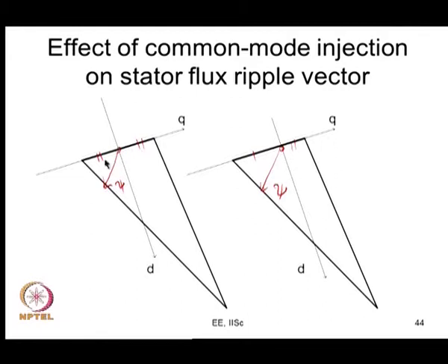So, dividing it equally is not actually optimal, it is suboptimal, but it is very close to what is optimal. Many a times when you are using continuous PWM, it is best that you divide that equally. If you divide that, what happens? The q axis current ripple reduces, therefore, the torque ripple reduces, of course, the overall current ripple also reduces now. So, this is one comparison.